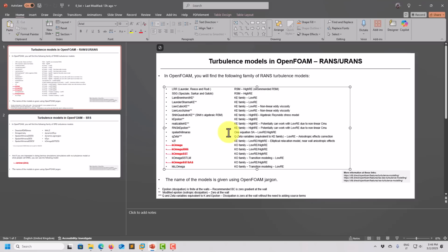We're going to go through the theory a little bit, and to mention that this is a low Reynolds, high Reynolds model, specifically formulated for turbomachinery and aerospace applications, but it is very general. You can use it for any application, but the origin of this model is aerospace. In OpenFOAM, it tends to work better for low Reynolds, but you can use it for high Reynolds. So we're going to go through the implementation and theory and then work the cases for low and high Reynolds, and look at boundary conditions and some other details. Now let's move to the theory.